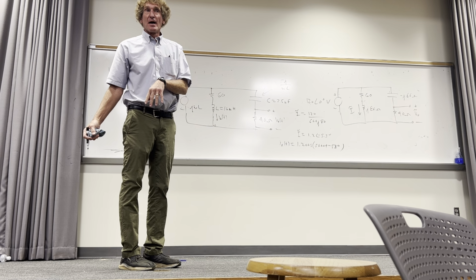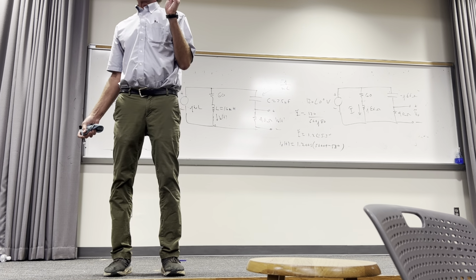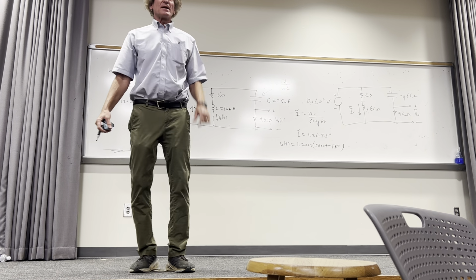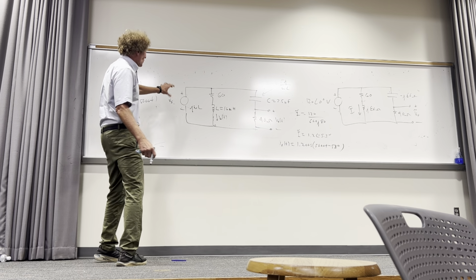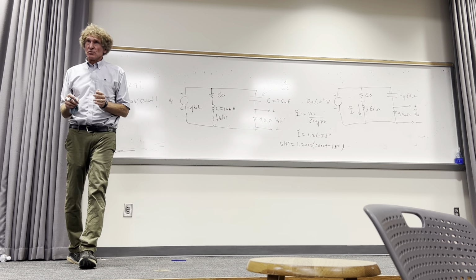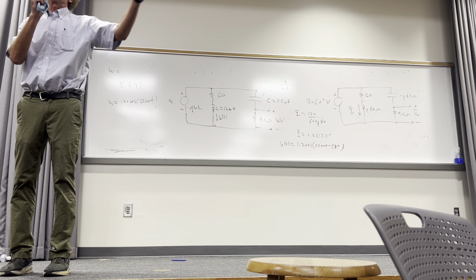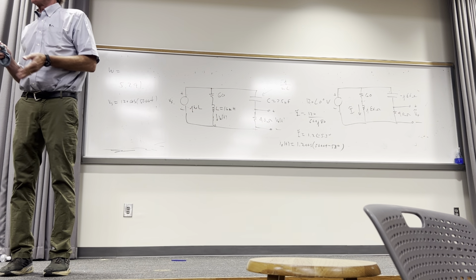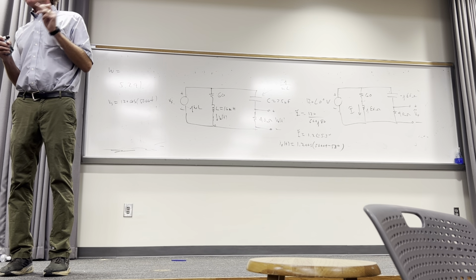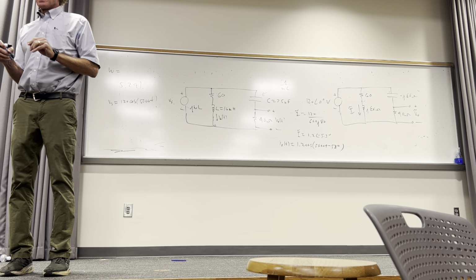How do you know if it's cosine or sine? Always cosine. Now this is an important thing. If they give a phasor of 20 at an angle of 30 degrees, it always assumes that's 20 cosine of omega t plus the phase angle. That is a standard in electrical engineering, and I assume for mechanical too. They use that as just a standard for phasor analysis. You with me, class? All right.